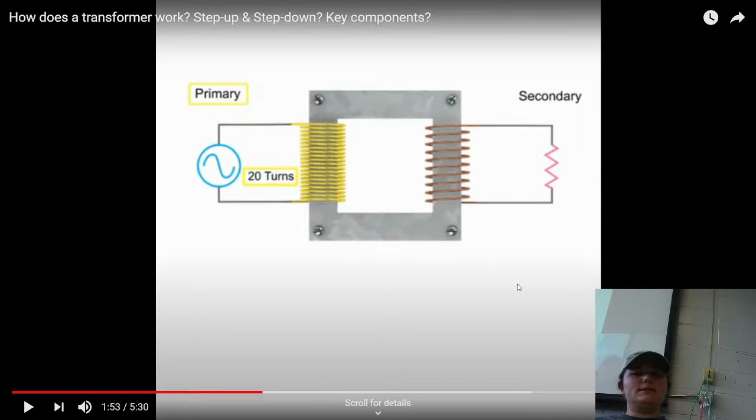So is this side producing more, you said ions, but you meant electrons, right? He's asking about the electrons, like the conductivity of the electromagnetic field. Okay, so the easiest way to think about this is every length of wire is going to have a certain amount of resistance. So if that has less wire, it has less resistance, right? So let's say that's a 20 to a 10. That means it's going to have half the resistance, which is going to do what to the current?